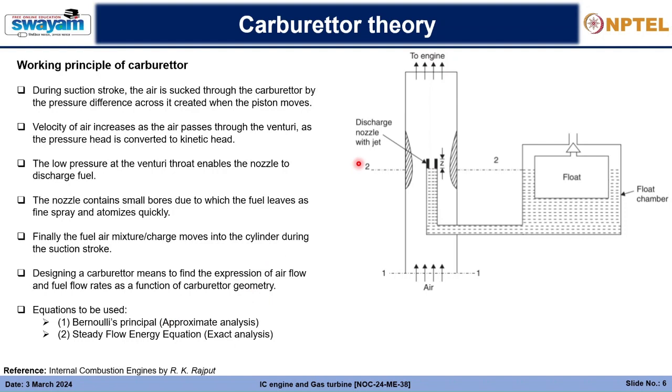But again, knowing both derivations is very important, and neither derivation for the airflow rate affects the fuel flow rate, because the fuel flow rate is completely obtained using Bernoulli's principle, because the fuel is still in the liquid state. So it is in the incompressible state, and for air that is not the case, it is in compressible state.